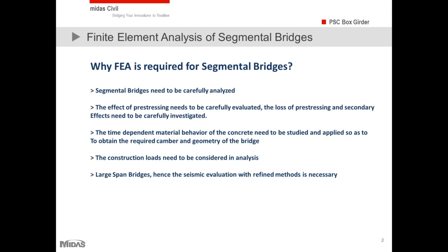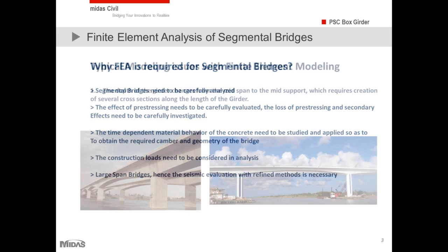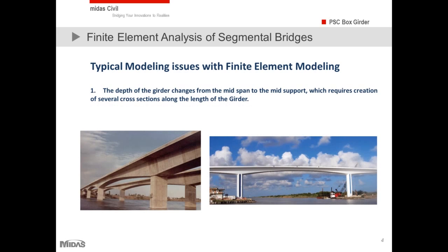Apart from these factors that I've already talked about here, there are several other factors that we need to consider for segmental bridges. The moving load analysis is more precise if you do it with finite element analysis. Similarly, the performance-based design and things like that, we need to perform using software by performing the finite element analysis. So these are some of the reasons why we need to perform finite element analysis to design post-tensioned segmental bridges.